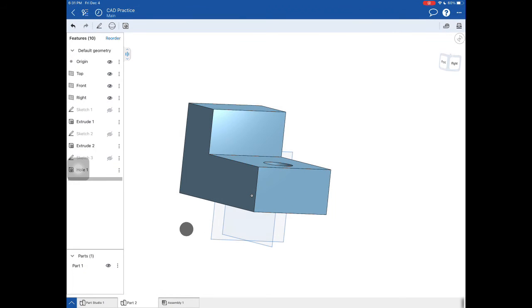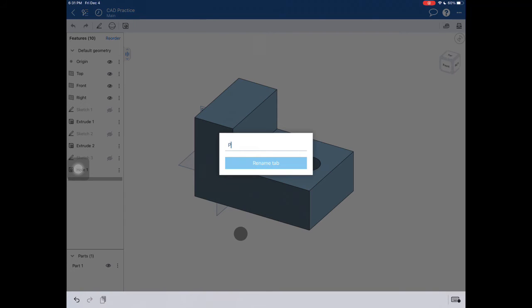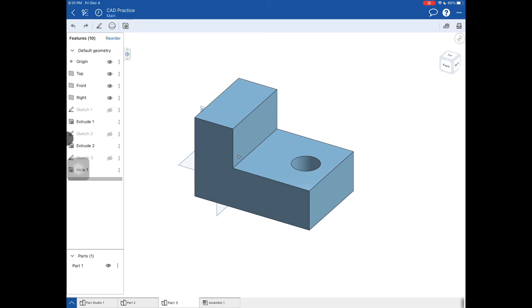So because the project we're working on is going to continue off and use very similar shapes, I'm now going to duplicate this one again, except I'm going to make some edits. I'm going to go to the left-hand side under Features, and you're going to see all those different extrusions or all those different sketches that I did, even the hole. So in our next one, I'm actually going to delete the hole feature because it's not in the new shape that I need to make.